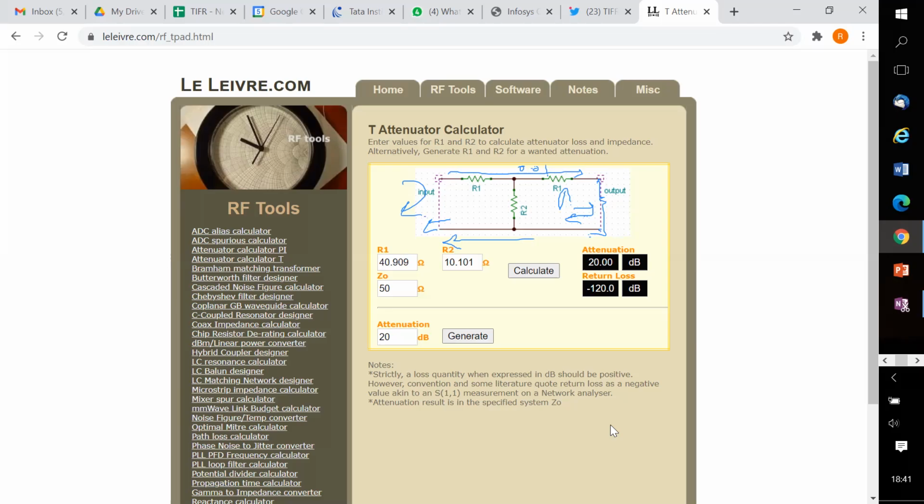The practical rule of thumb you learn from this is that if I take an attenuator and measure the resistance across its center pin and ground, for larger attenuators it will always be 50 ohms or very close to 50 ohms, because it doesn't require this part of the circuit to give you that 50 ohm matching, because the power absorption is.